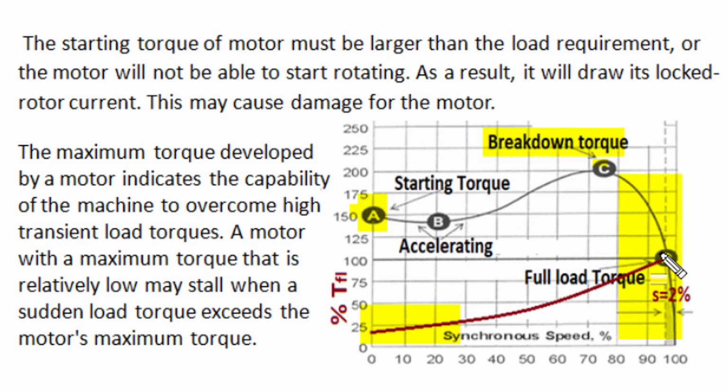So if accidentally torque requirement on motor gets doubled, even in that condition motor will remain in running position. But if torque exceeds beyond 2 times or supply voltage has reduced and torque has increased simultaneously, then in that case if pull out torque becomes less than the load torque requirement, the motor has to decelerate and it will all of a sudden stall, and this is a dangerous position and a trouble to our manufacturing setup. So if there is a chance of sudden increase in motor load conditions, then we have to select a motor of higher breakdown torque, either NEMA design A motor or NEMA design C motor.